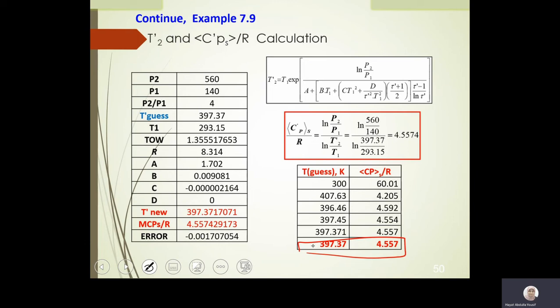You need to remember that I gave you two equations at the beginning of this chapter, from chapter 6, and I told you for the pump, please accept those equations: delta H is not equal to CP dT, but CP dT plus a correction. And same thing with dS. It's not CP dT over T, but plus a correction, and that correction considers the effect of pressure in the system. This is how to calculate enthalpy and entropy for liquids. So those are the two new equations here.